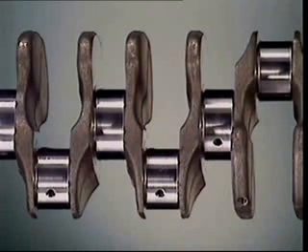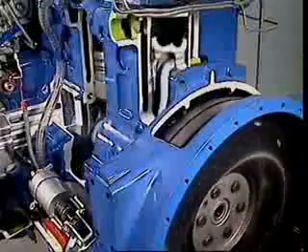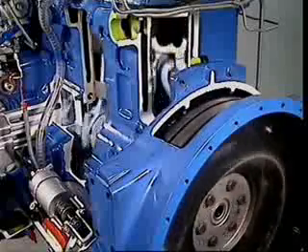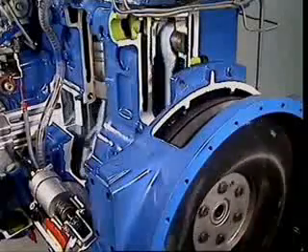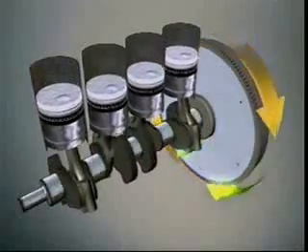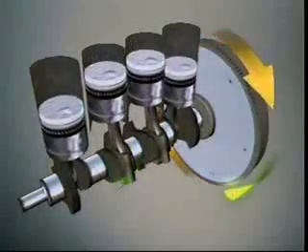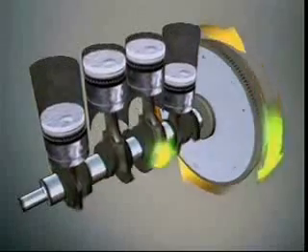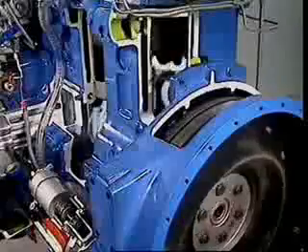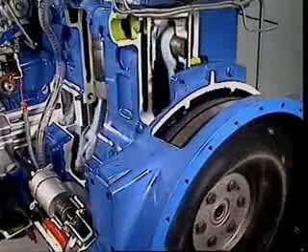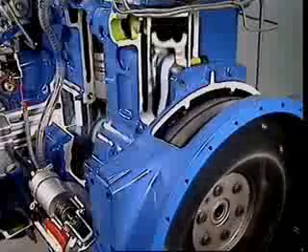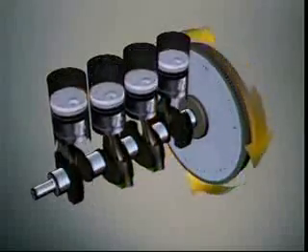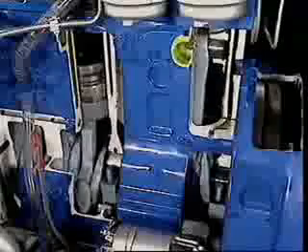On the rear of the crankshaft of both the 4-stroke and 2-stroke diesel is a heavy flywheel. It stores energy from the power stroke and gives it to the crankshaft to help it keep turning. In a 4-stroke, only 1 stroke in 4 delivers power. The energy from this 1 power stroke has to turn the crankshaft through the other 3 strokes. Without a flywheel, the crankshaft would slow down and stop. In a 2-stroke, the same principle applies, but every 2nd stroke delivers power.